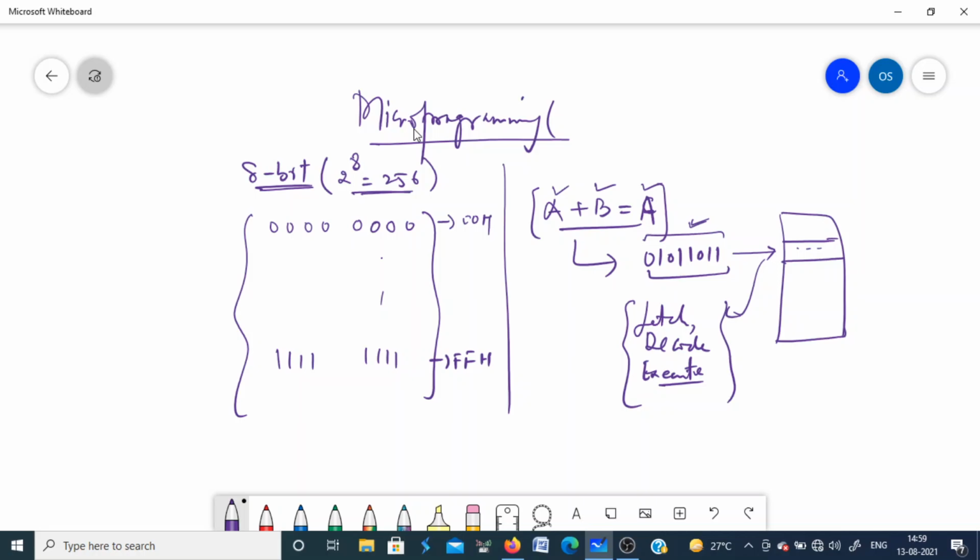It means whatever is the machine code for one processor is not compatible with another processor, because they are designed by different engineers, and it may be possible that one processor uses this code for addition, while another processor may use a different code for the same operation. So in one more processor, this may be the binary code or machine code for addition of two numbers in A and B. That is why when you write a program in machine language, it is not transferable or executable. One machine code for one processor is not transferable to another processor by different manufacturers, because their machine codes are different.